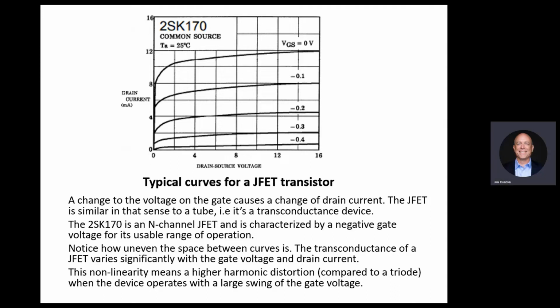But if you set a JFET at a very high current point, like a high bias relative to the signal that is coming in, the changes are negligible, and you get low distortion, more than a tube, but acceptable level.